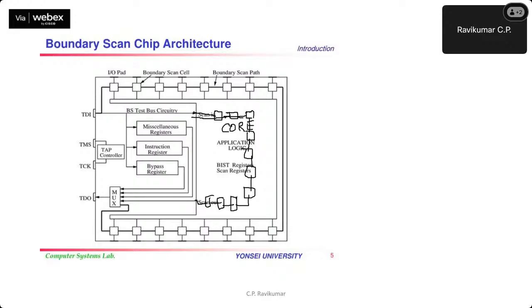They would give a protocol and say, first you have to initialize a particular register using your TDI, TDO, and then you have to give an instruction. That is the reason for this instruction. This instruction register may help you to start the test. The test could be a scan test, or it could be logic based, or it could be memory based. So that is that test instruction.